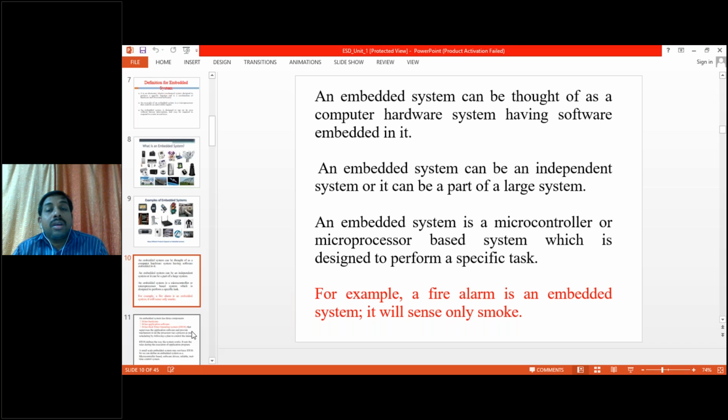So like that, there are many embedded systems in a big system. Like in our automation system car, we are using an ignition system, headlamp controller and airbag control system. So thus we can define an embedded system as a system having hardware and software and doing a specific task. Now you can design your embedded systems with a microprocessor or microcontroller base. No need to be a microprocessor, you can go for a microcontroller. A microcontroller is a processor with inbuilt memory.